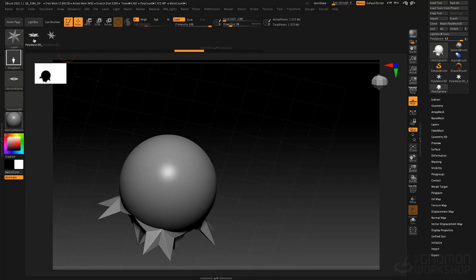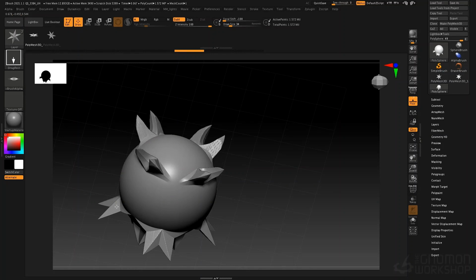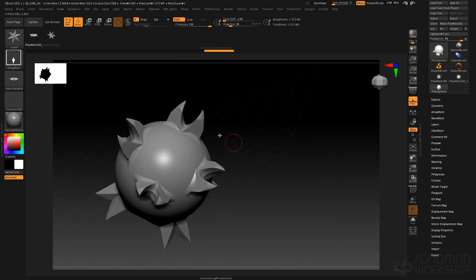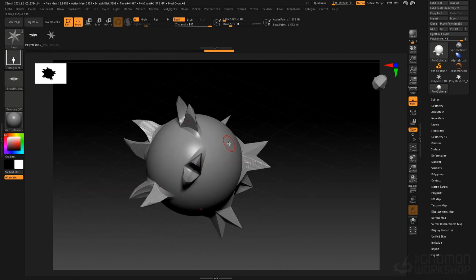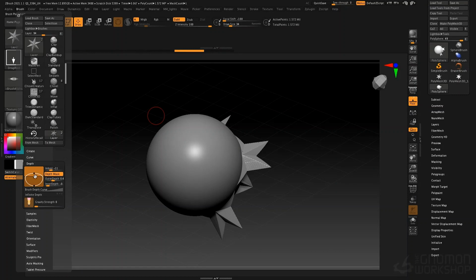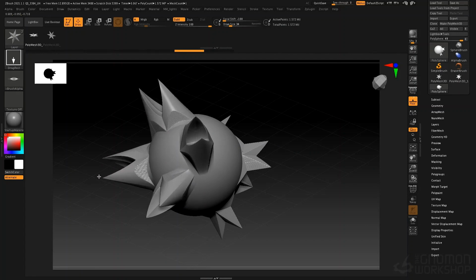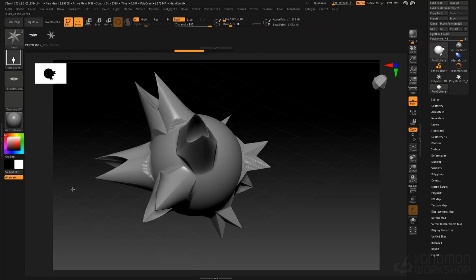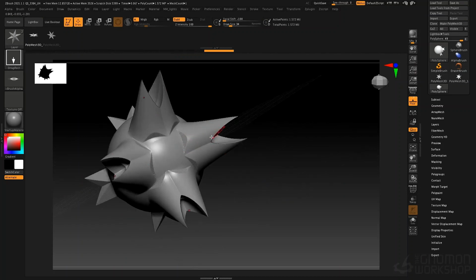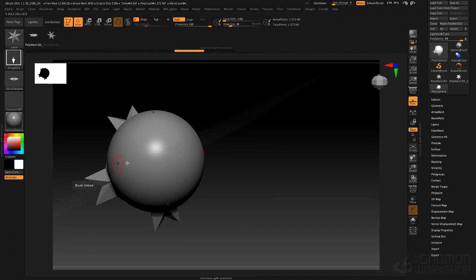Let's switch over to our other orientation. Go to brush, let's bring the depth down, and then try this one. And this gives us this very interesting sort of spiky curvature here. It's clipping off the edges there. So we'll undo that, go back to brush, and let's raise that depth control a little bit more, and then draw that out again, and you can see the differential we get. Now if we keep pulling this out, it's going to keep limiting based on how far off the surface this alpha starts to push, because again, it is depth masking the effect of the brush.